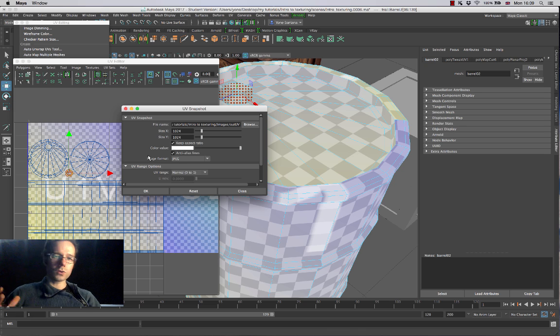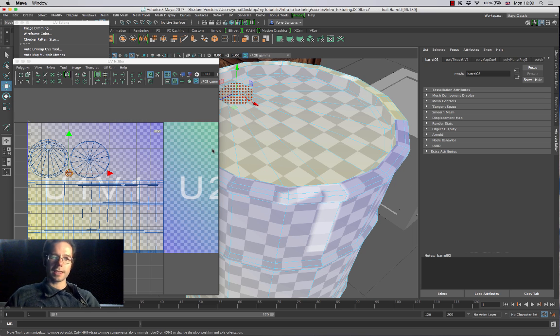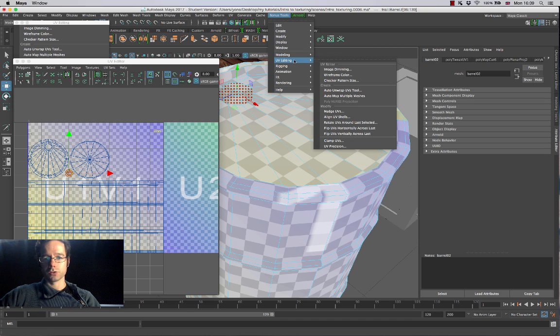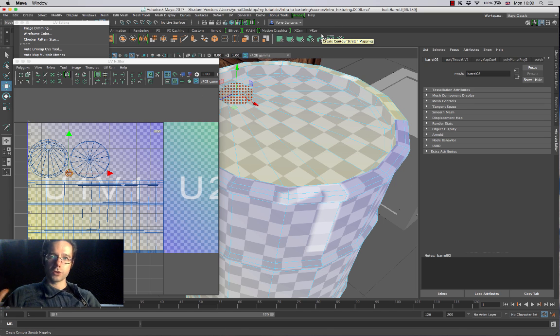So with that, we've got a huge selection of tools that we can work with inside of Maya, and you'll see that this process of building UVs is just a little bit labor intensive, but you're going to see that all the projection methods and all of the unfold tools, even this amazing tool inside of the bonus tool, is remarkably useful, and there's some other little settings in here as well. So importantly, UVs have to happen before we unfold any part of our object and before we can even start considering doing some bitmap texturing inside of programs like Photoshop or any image editing software.